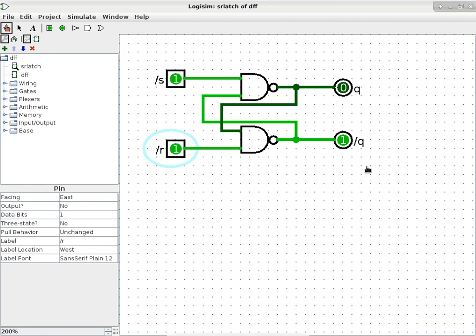As it turns out, it was a software issue. The manual specifically says to update this register first, and then update that register. It should be in this particular order. Whoever wrote that code, and I knew exactly who that was, decided to flip the order. With the correct order, the older die design has an internal lock circuit to make sure a race condition does not happen. But when you flip the order of updating those locations, then a race condition can happen. The older die using bigger transistors masked the issue. The race condition was in favor of the quote-unquote correct sequence.